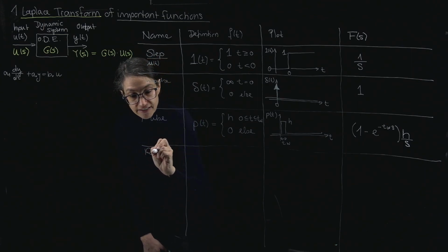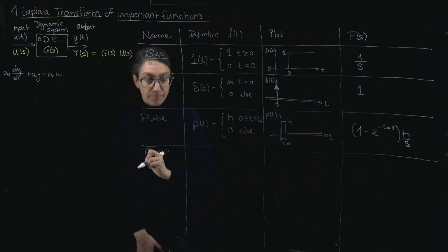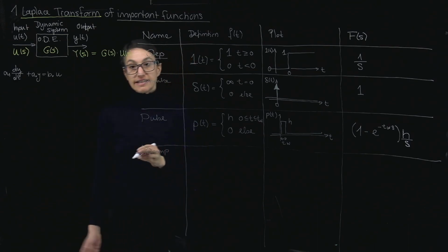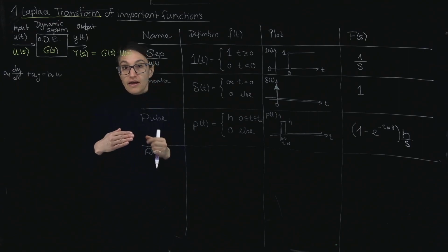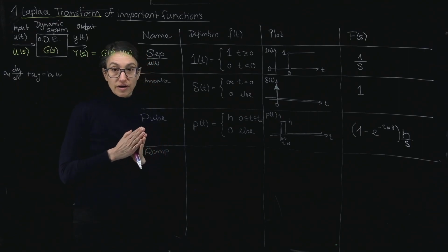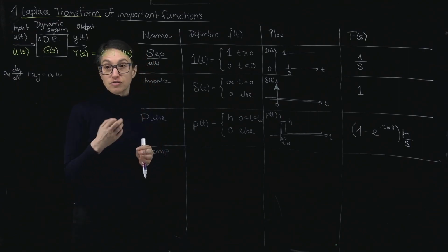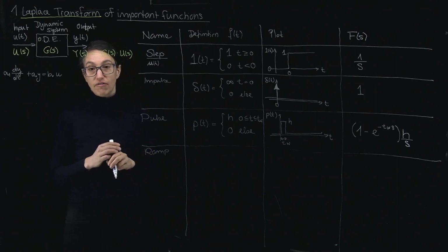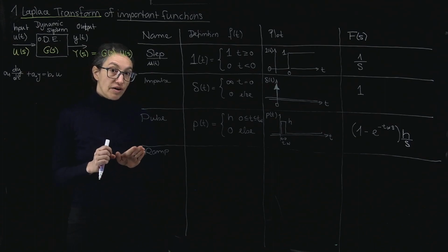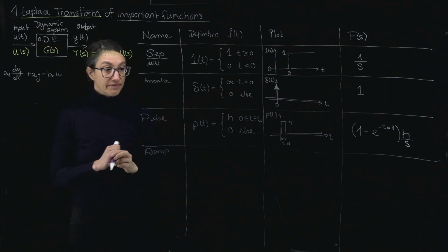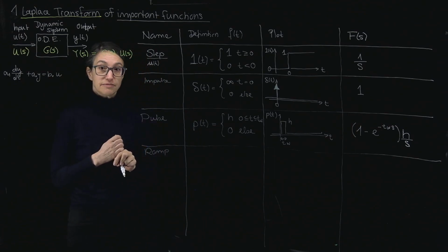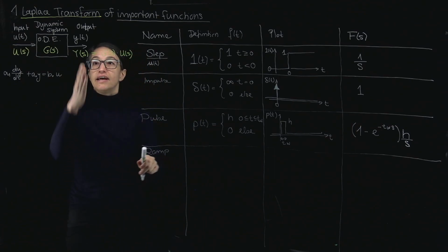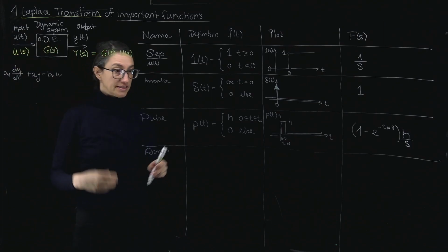We have a signal that we call a ramp. And that can be an input signal. Sometimes we don't like to put a pulse onto a system because we may damage our actuator, our valve, or our motor. So what we would like to do is ramp it up slowly. And it could also be an output, which we'll see later in the video in an integrating process. So the ramp function can be an output signal, and can also be an input signal.